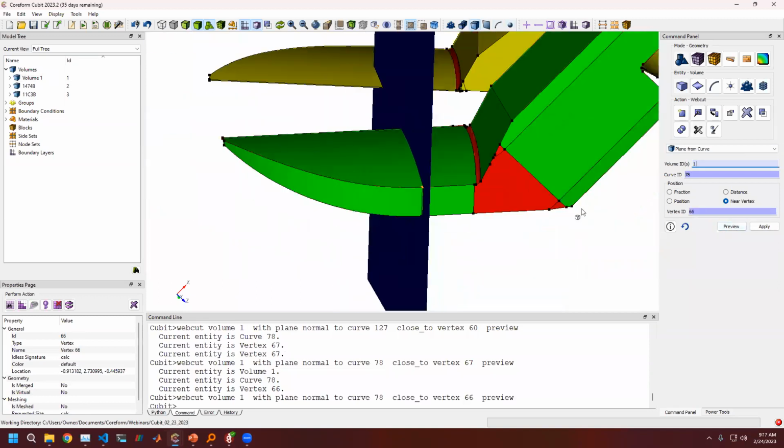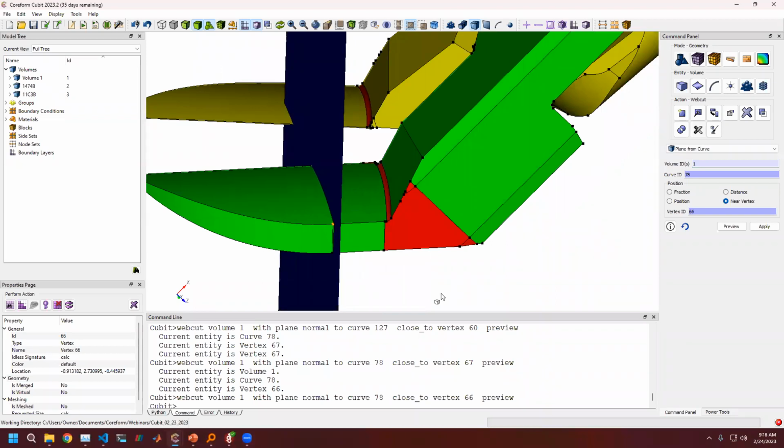And again, try to push it off as much as possible. That's just one tip to try to avoid exacerbating the dirty geometry that you might have, because as you do those cuts, you can do more and more damage to those spline surfaces. So that's just one little trick I like to do.